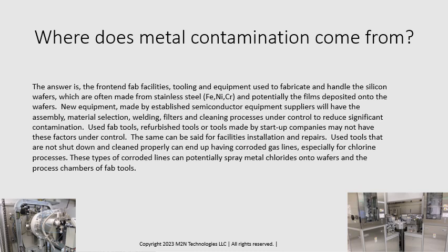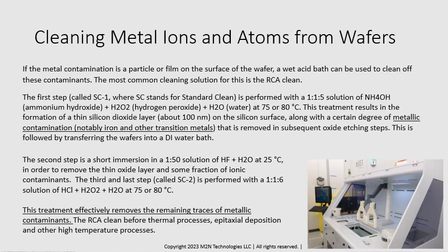So that's one common thing. We found that just running wafers on belts and chucks that may have stainless steel particles, they'll transfer to the back side of the wafer just via scratching and can rapidly diffuse through the wafer during the first high temperature thermal cycle. So there was a lot of work done in the equipment industry to avoid contacting silicon with stainless steel.